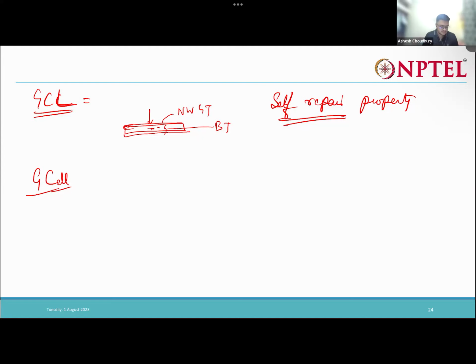It reinforces the soil with the help of confinement. Okay, in a simple way, to understand this confinement property, say you have a soil specimen and you are doing the triaxial test. Say sigma 3 is equal to 0, meaning the cell pressure is 0. There is no confining pressure.